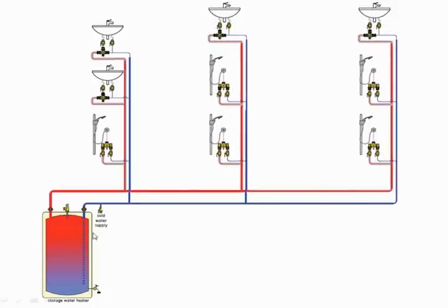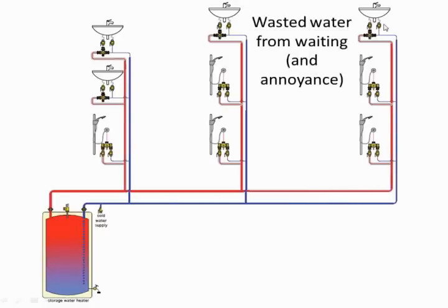But when you start getting into more commercial systems and there's a long run between your source of hot water and where it's being consumed, the heat loss in these pipes could result in a significant wait for hot water when someone turns on a shower or bath or a faucet. There's the annoyance factor and also the wasted water factor, and water is getting more and more costly, as we all know.